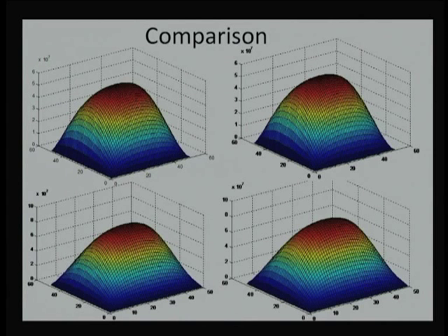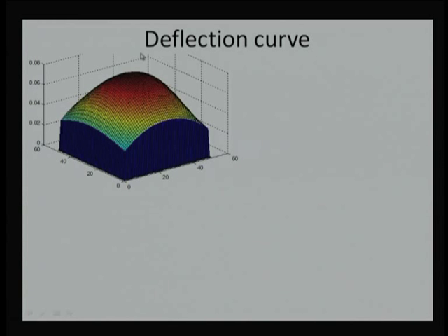Now, the time has come to find out what the elastic deformation will be. So, this is elastic deformation. What is being done over here? We calculated the pressure at every node and simply found the deformation, without going through the iteration loop and without accounting for it in the film thickness expression. This has been done only once: we know the pressure, find out the deflection at every node, and we know the 50 by 15 nodes. At the initial point there will be 0 deflection because the pressure is 0, after that it goes high and reaches some maximum value.